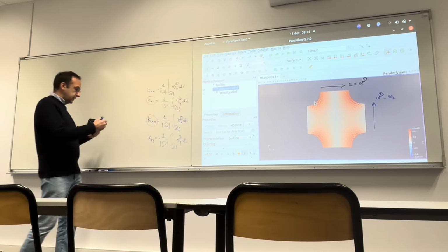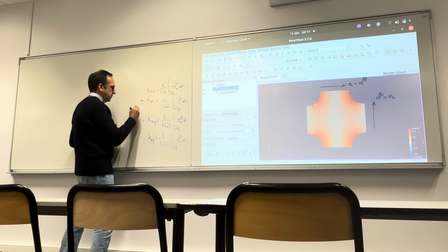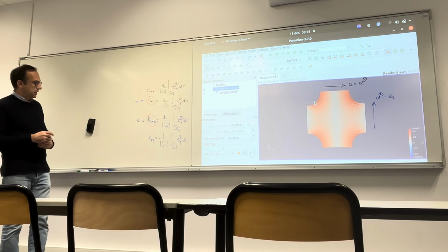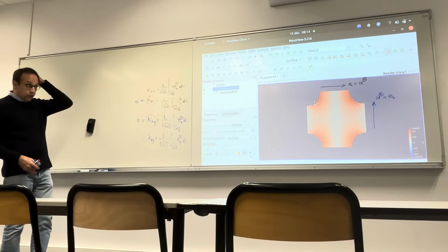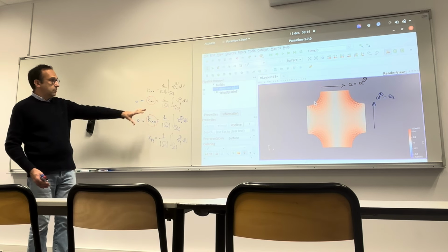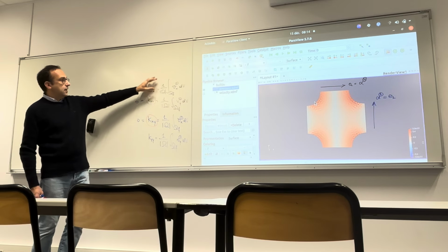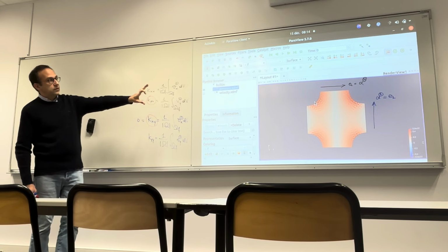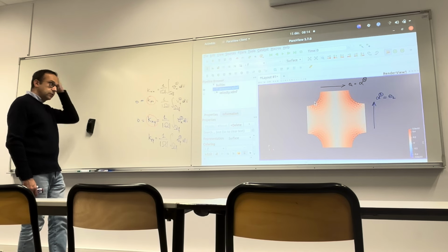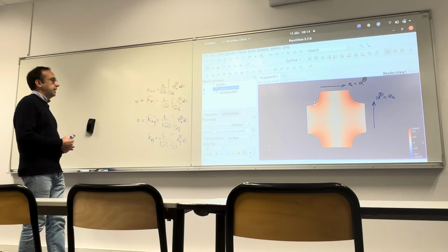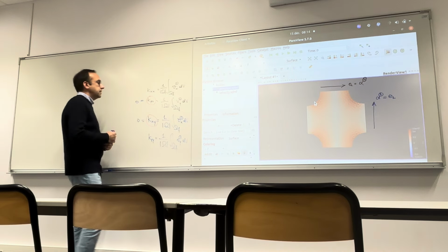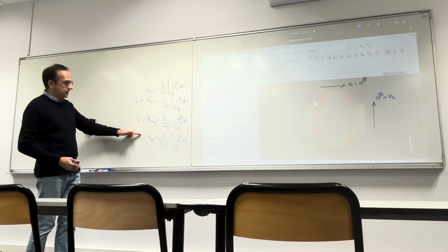what we get here is that these two are 0. Almost 0, I mean 10 to the minus 6, 10 to the minus 9, with respect to a unit, or consider that here everything is dimensionless, so I was working with a unit square, to simplify as much as possible. Also, the viscosity has been taken equal to 1. In any case, these are 0, and these kxx and kyy